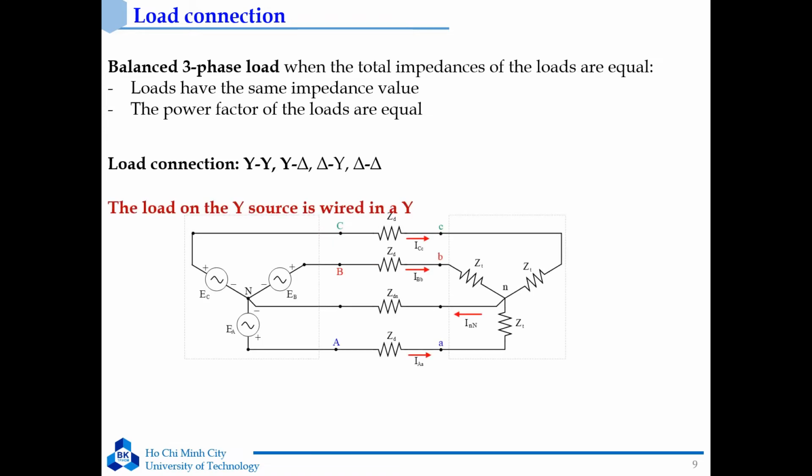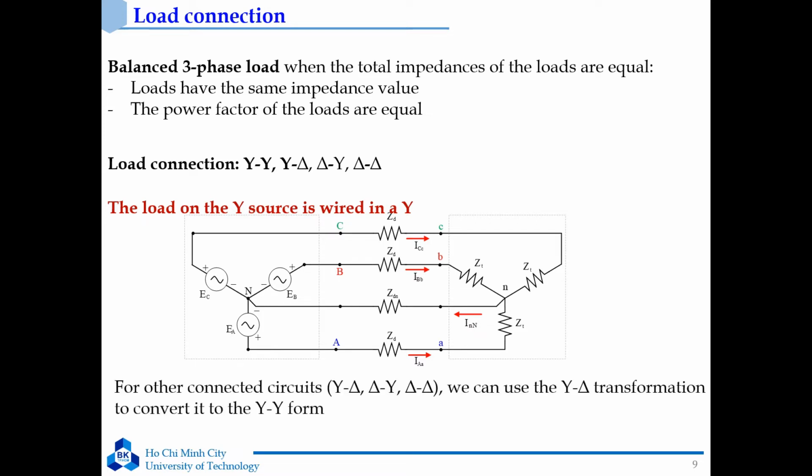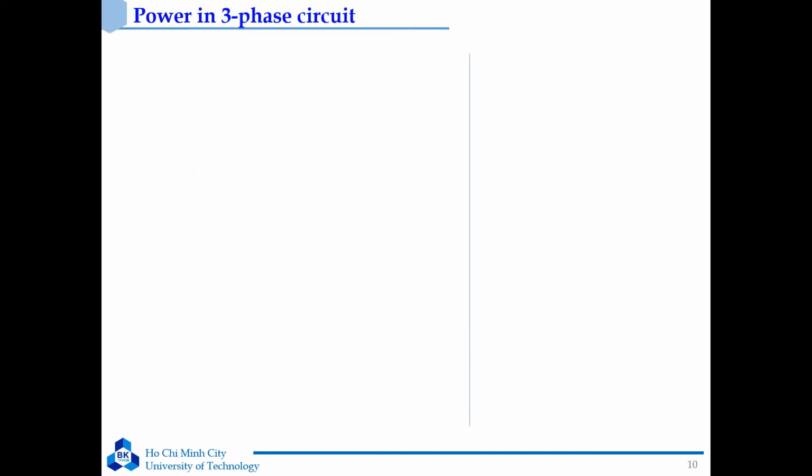You can see in the figure the Y source connected with the Y load. You can analyze this figure by using Kirchhoff's law and Ohm's law. For the other connection circuits, Y-delta, delta-Y, and delta-delta, you can use the Y-delta transformation to convert them to the Y form.